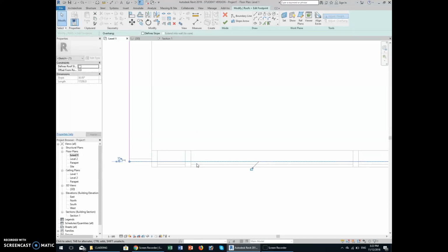Sometimes the structure of your curtain wall will stop in the slabs and will be hanging there. But the glass will continue and the exterior part also. Sometimes your whole curtain wall will go from top to bottom, sometimes it will stop. But this is part of your project. This is what you have to understand. That's why it's so important to do the detail first by hand. Okay? Because the program doesn't know the real thing, so you have to do it manually.